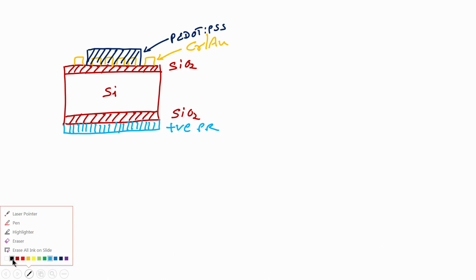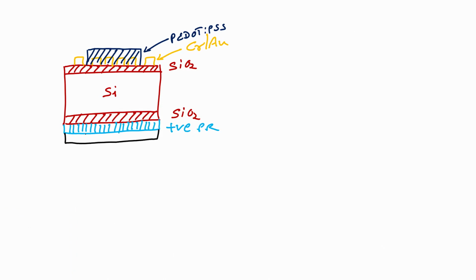After soft bake, we will load a mask such that my photoresist will protect the area of my interest and the remaining area will be etched after I expose this wafer with UV light and develop it in the photoresist developer, right.